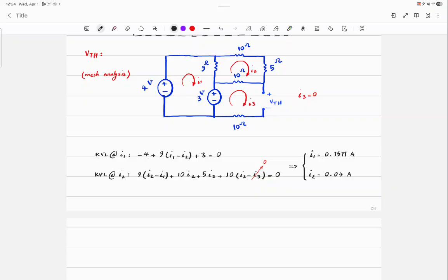Always remember what you're looking for. What kind of animal is it? Is it voltage, current? What is it? Voltage. What do you do when dealing with voltages? Either you go for Ohm's law or KVL. So can I apply Ohm's law to VTH to find it? No, it's an open circuit. There's no resistor there. How about KVL?